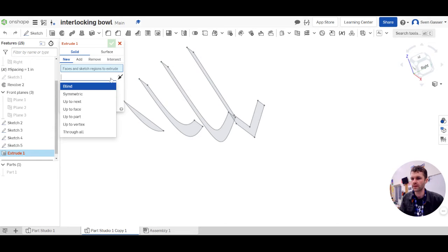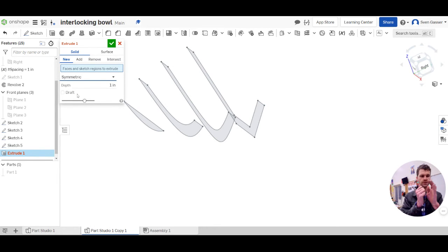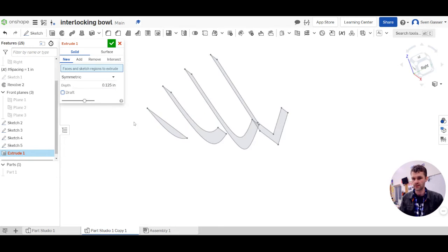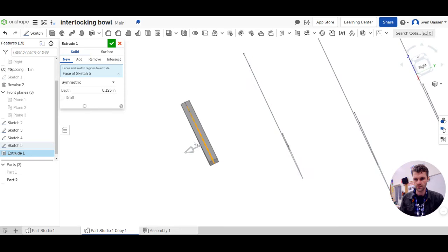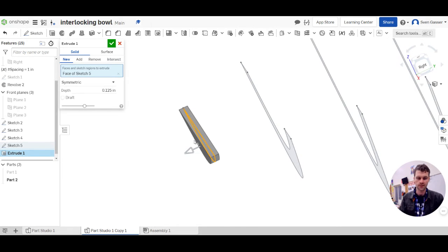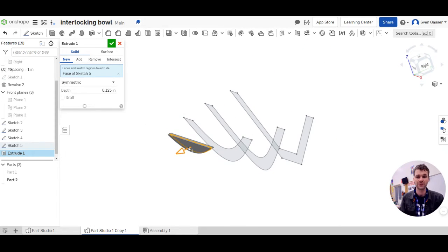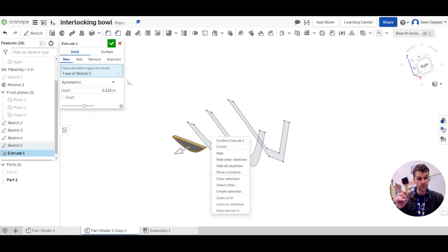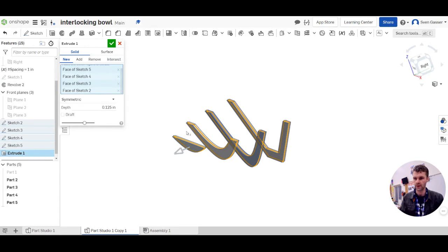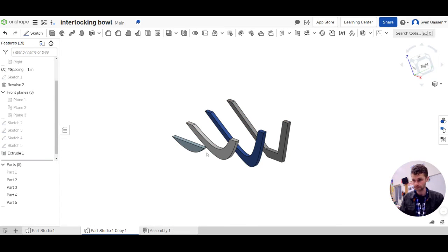It's kind of important that we do a symmetric extrude, which means instead of just having the surface and extruding in one direction, we're going to have the surface where our drawing is and extrude both directions to get the total thickness. You'll see what that looks like here. Again, that's the thickness that we always use. That's the thickness of the material. You can see the sketch is in the middle, and it goes both ways to get to the thickness that we want, just so everything stays symmetrical as we line things up here. The good news is we can do all these parts in one extrude. So we can boom, boom, boom. I got all those parts right now, and I'm saying, yep, I'm good.